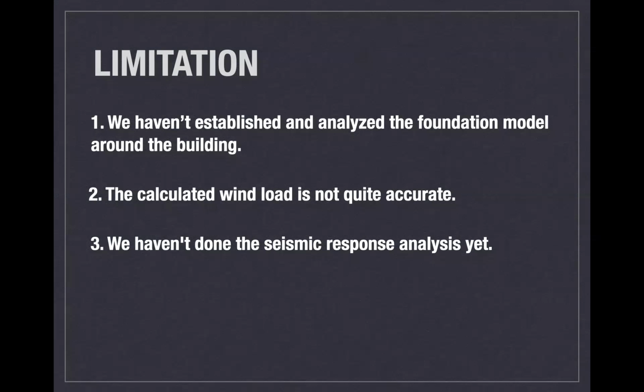And I roughly calculated the magnitude of the wind load on the model, because the surface area of the model cannot be determined. It's curved, so I approximated the surface as a plane, and I assumed that all the forces on the windward surface are pressures, so I don't need to add any numbers. And then I ignored the characteristic that the wind load shape coefficient changes with height.